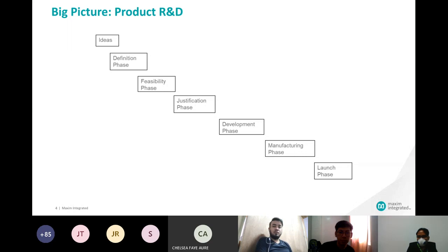So Hex is going to do a board level design, to interface from the wafer or from the package part to the automated test equipment. And then she's going to do software as well, because there are power supplies on your automated test equipment. There are power supplies, oscilloscopes, signal generators, voltmeters, ammeters. So you have to send instructions to all those equipment so that you're able to test the device under test or the wafer.